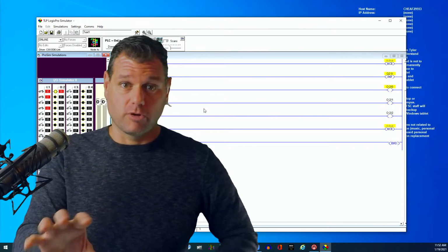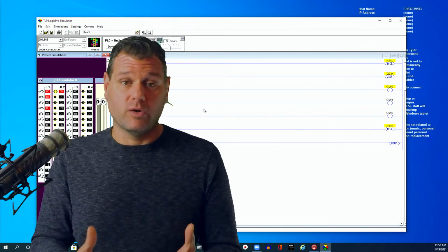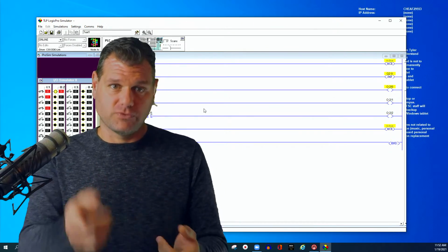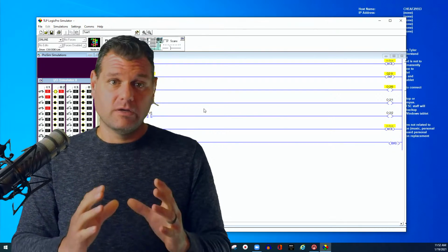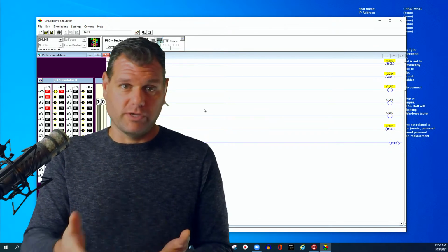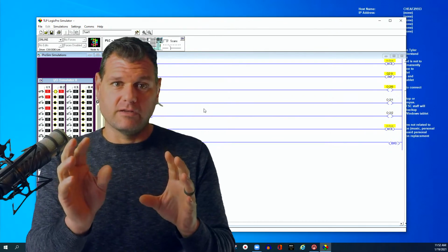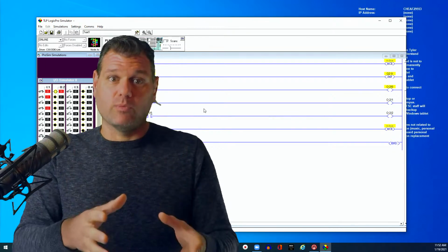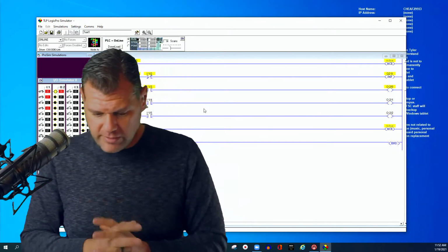So my last instruction to the burner was turn on. But I never went back and told it to turn off. Now you could write code and say scan one more time and do that one last thing. If this one's false, do a one shot and completely scan this one more time to make sure everything's cleaned up. You could do that. But basically, the best way to do it is to use internal bits, the B3s, your internal data bits, and trigger something in the main. And then the main would then have it. So the main would typically be all your outputs, all your safety systems, all that stuff would be in the main. So I'll leave it there.